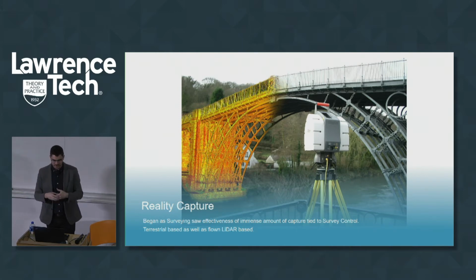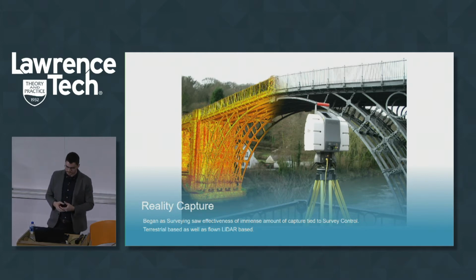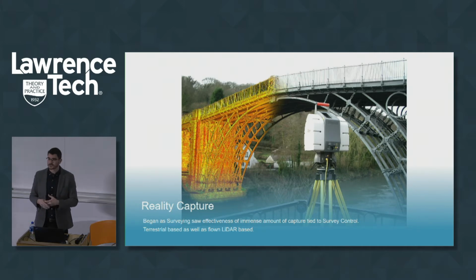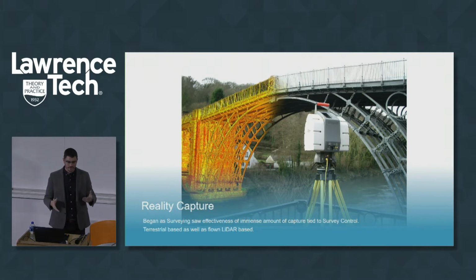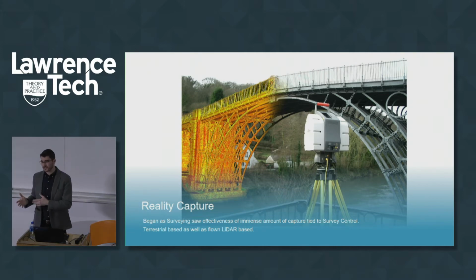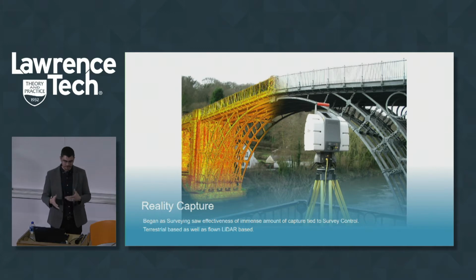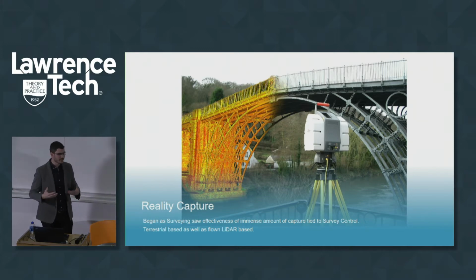And so this technology is also known as LiDAR, light detection and ranging. And the initial grab for the reality capture industry was more accuracy, farther range, and potentially quicker scan times, easier to scan. So some of the technologies that just came out recently, they're able to scan almost a mile and get sub-centimeter accuracy with these laser scanners. But you have to sit there and watch this thing scan for about 20 minutes to get that data. So this data has really proven itself as incredibly effective in giving you that multitude of data that you're not used to. And I think this is a good first example of how we've been bombarded with so much data in our industry too.